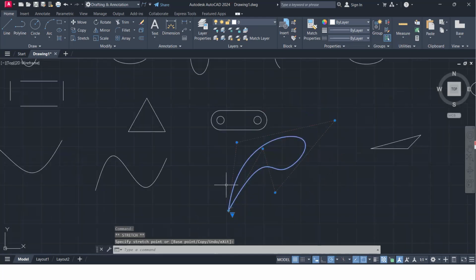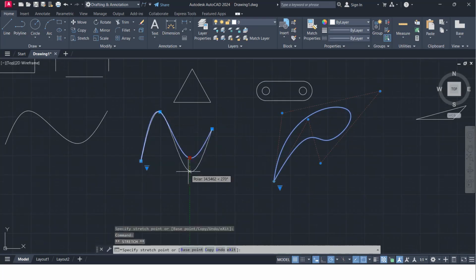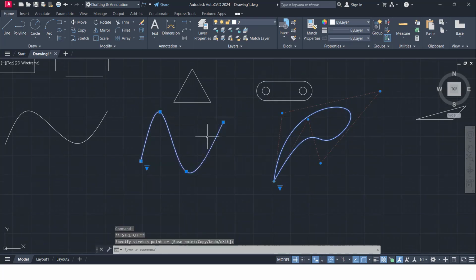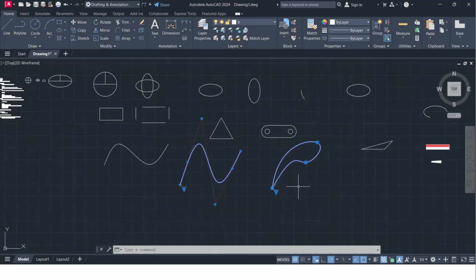And for the contour fit here, we have the points on your line, the spline. When we click on this, we can adjust this part also. You can also convert this in the form of the CV control vertices. When you give the CV, this is your CV way. If you want it in the form of control fit vertices, then you can have the fit options right here. Both the options we can convert by use of this portion also.